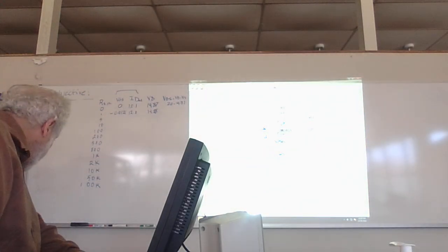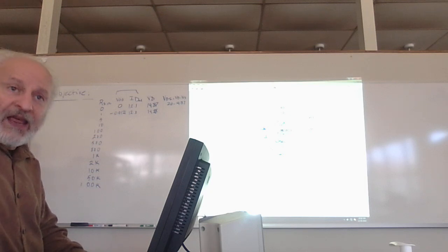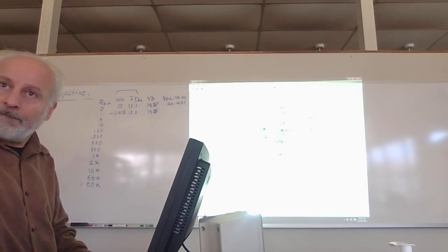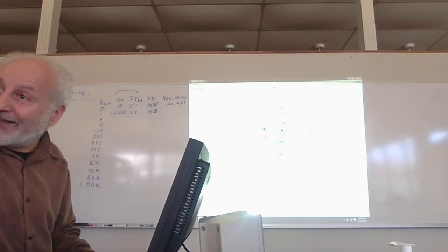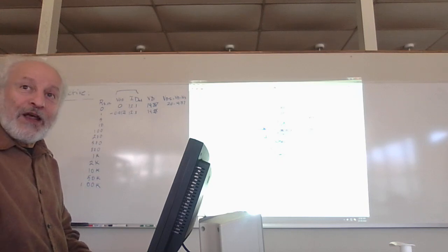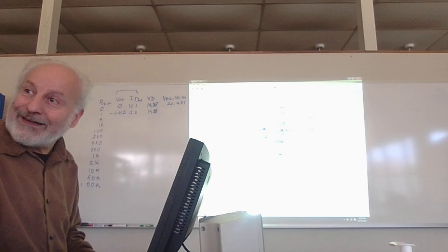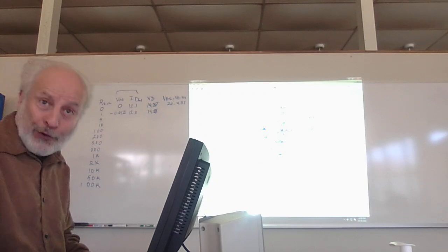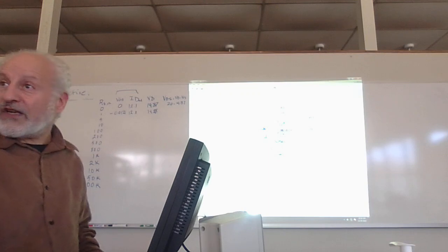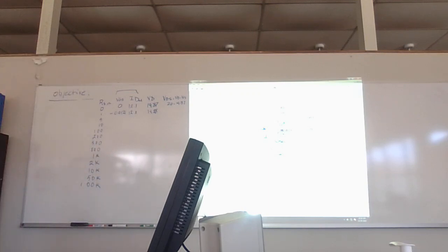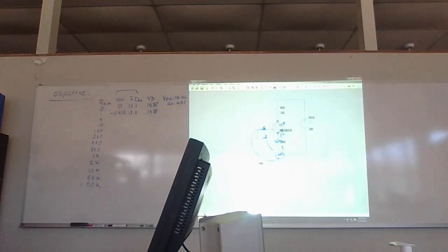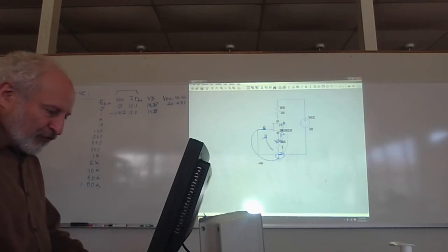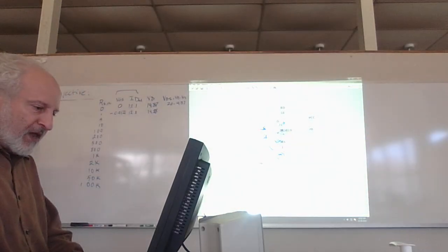So maybe instead of going from 50 to 100K, go 50, 80K, then 150K. Does that make sense? And then put a meg on just to see what happens. You're not going to reach zero exactly. You with me so far? As far as ID is concerned, it will tend to go towards zero. It's pure physics. You're pinching, but there's still something leaking in there. There will always be a leak. It will be very tiny, but it will be there.